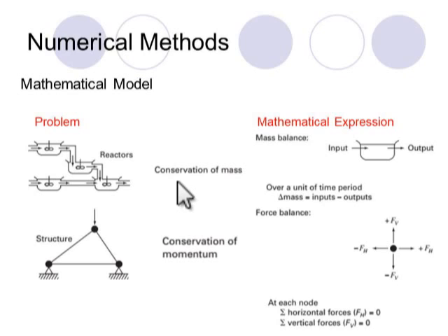Okay, so this is the problem that we want to solve. We need to predict the mass flow rate or the reaction rates or whatever it is. Then what is the mathematical tool if you want to design such a system? Of course, the conservation of mass, because the mass that gets into the system has to be equal to the mass that gets out of the system. Otherwise, you need a very, very big or infinitely growing vessel.